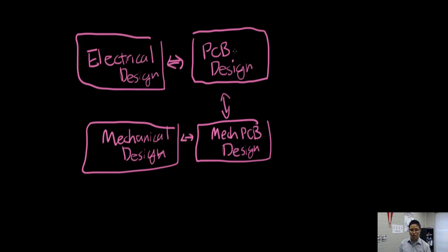So are you going to have mounting holes and standoffs? If that's the case, start while you're doing the PCB design, since you're going to have, say, through holes in the corner. Have the mechanical portion of how you're going to mount it as part of your design process.